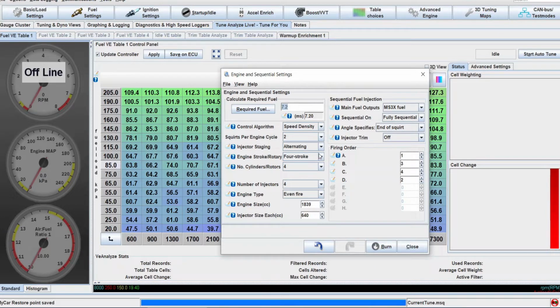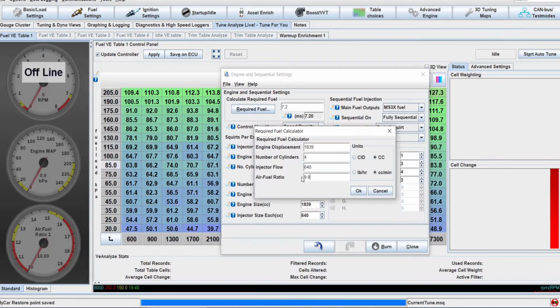So yes, this can kill several birds with one simple change. It will affect the cranking and acceleration enrichment and the various other things that I mentioned before. So this is the one place that you can modify your air-fuel ratio and have it mostly be okay, that you don't need to change anything else, because on this screen, air-fuel ratio is just part of a calculation. It's not used otherwise. It's the other screen that controls how the air-fuel ratio is used to control fueling dynamically.